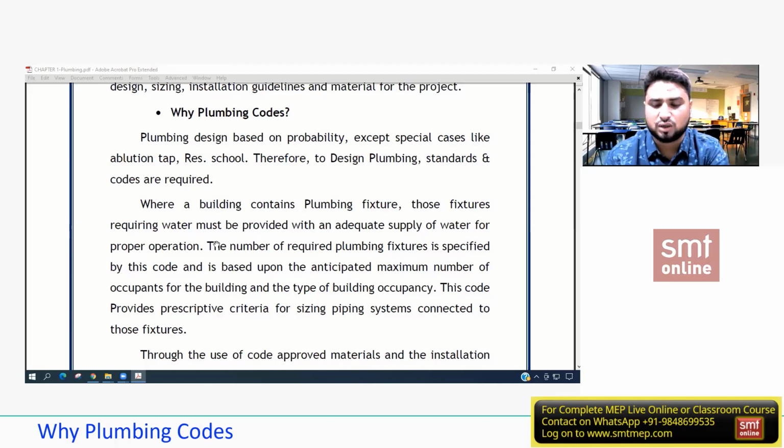If the water is not supplied at what exactly the fixture is asking for, then this will cause discomfort. And in plumbing, always remember there are two things whenever you size a pipe. Oversizing is not accepted. Undersizing is also not accepted. What happens in oversizing? First of all, you're decreasing the velocity because you're doing expansion of the pipe. For example, a 1 inch pipe is more than enough. If I'm going with 1 1/4, automatically I'm giving a wider pipe. So the velocity drops, isn't it?